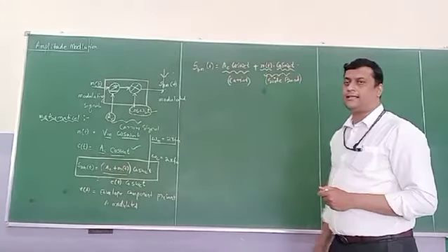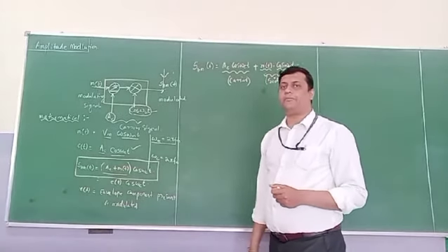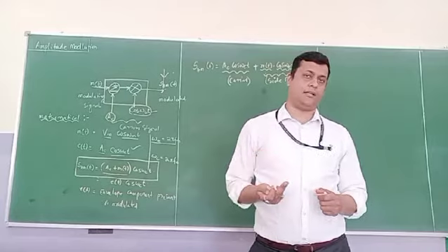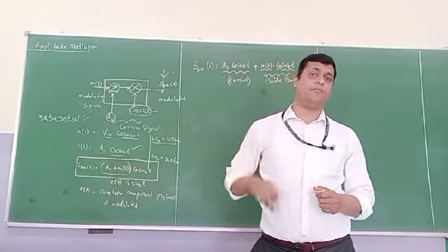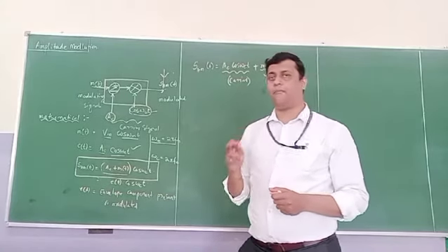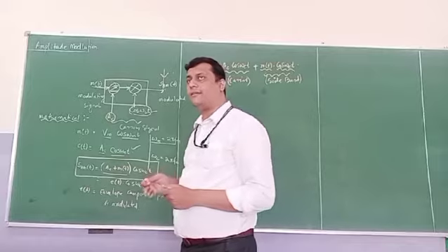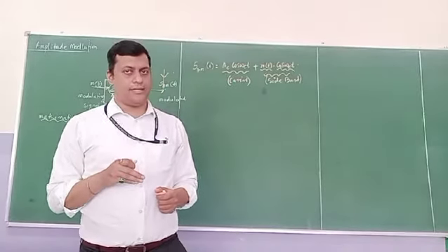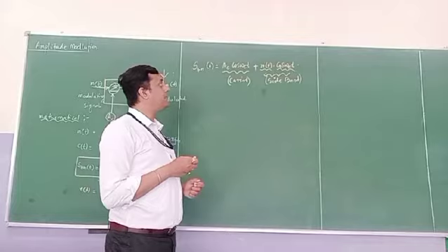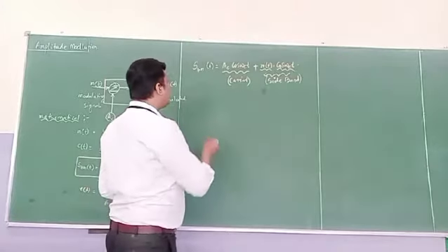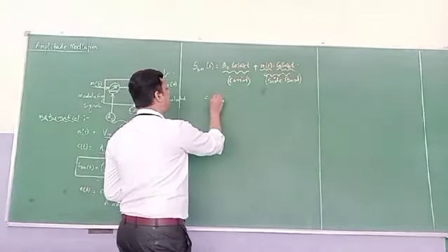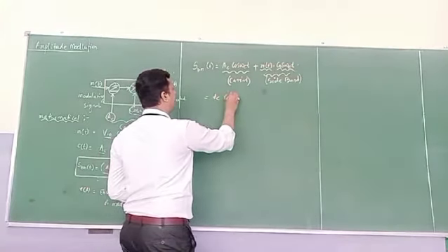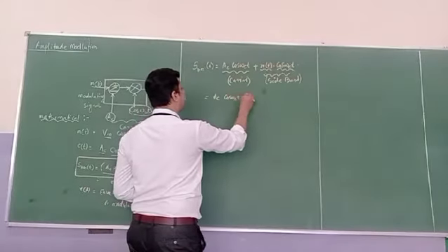So that means in the AM signal we have three different components. As in the PPT that I have shown, the first component is the carrier, the second component is the upper sideband, and the third component is the lower sideband. How to identify these sidebands? Let's see. So here, if I expand this, it is A_c cos(ωct).